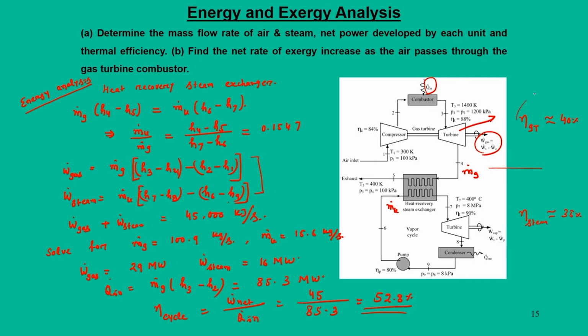But when you combine them with this given data, a simple analysis will tell you that efficiency is enhanced. Of course, we can obtain power from both units. So, the energy analysis says that the combination of steam and gas turbine units is essentially justified. This is about first law analysis.